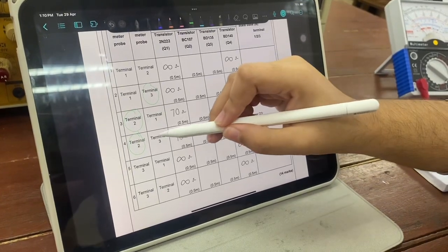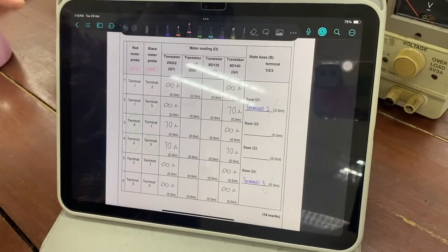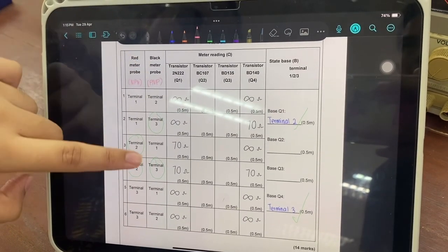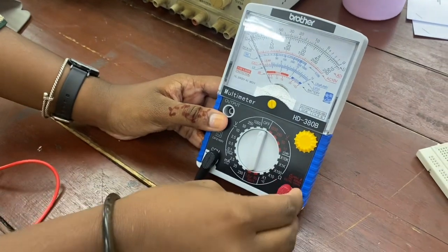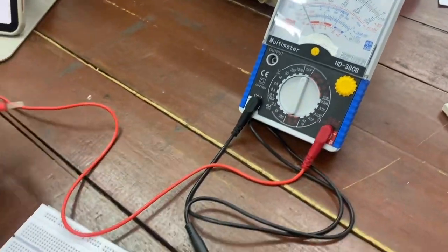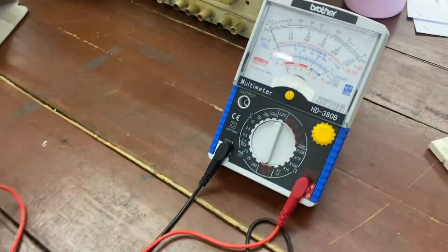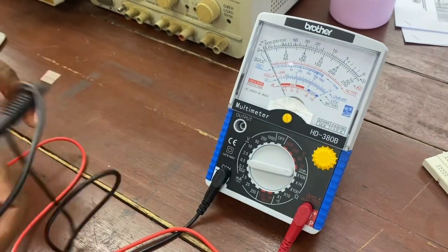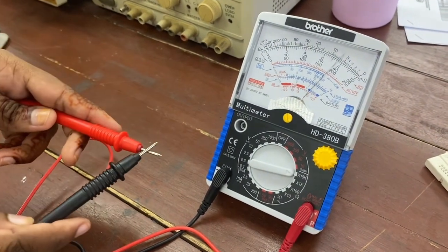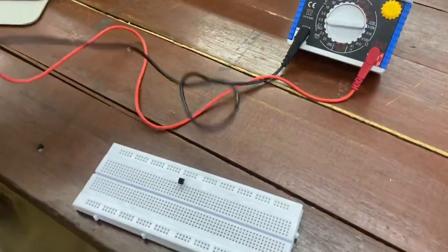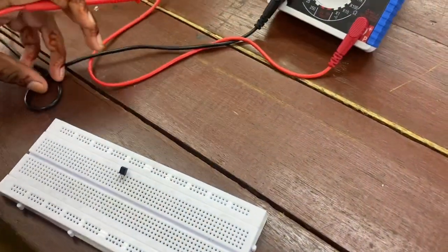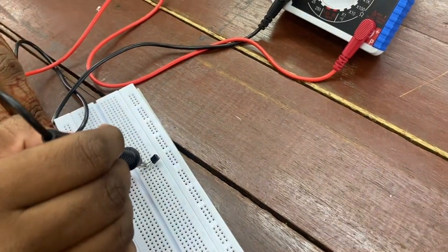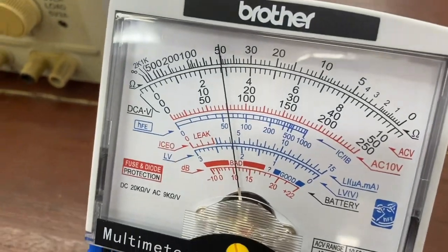In a PNP transistor, the emitter is P-type, the base is N-type, and the collector is P-type. Here, the base-emitter junction is forward biased by applying a negative voltage on the base relative to the emitter. Holes flow from the emitter to the base, and most pass through to the collector, creating a current from emitter to collector. The current directions are reversed compared to NPN, in which IE flows into the emitter, IB flows out of the base, and IC flows out of the collector.